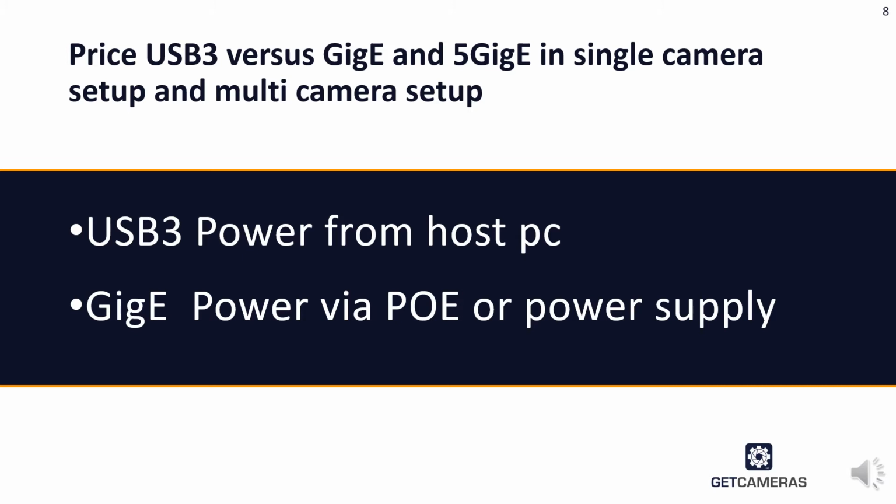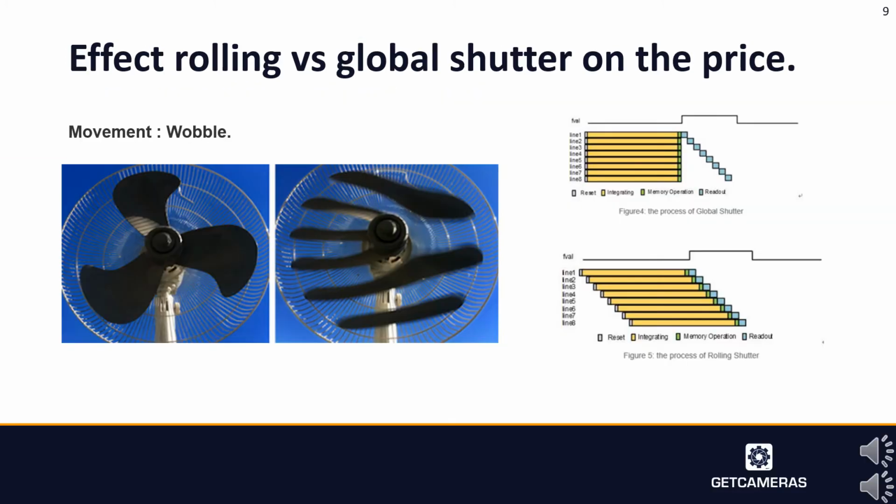So one camera you will connect for sure, 2 cameras you may still be able to connect. When it comes to gigabit cameras, usually a PC does have only one network port. So already when you have 2 network cameras, you more likely need to invest in hardware to connect both cameras at the same time.